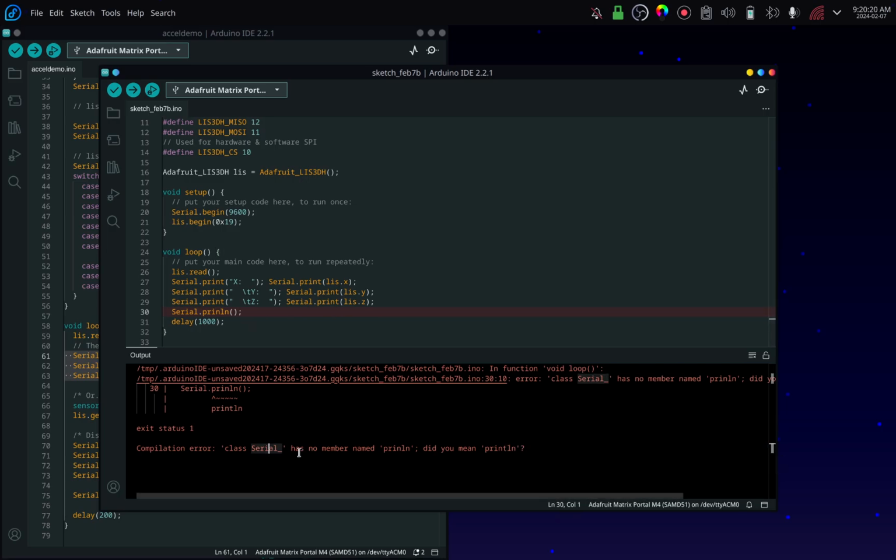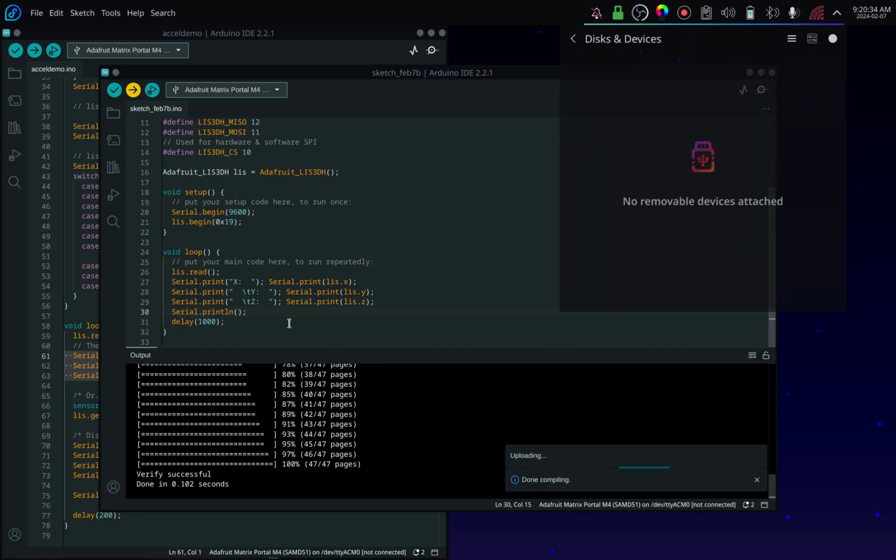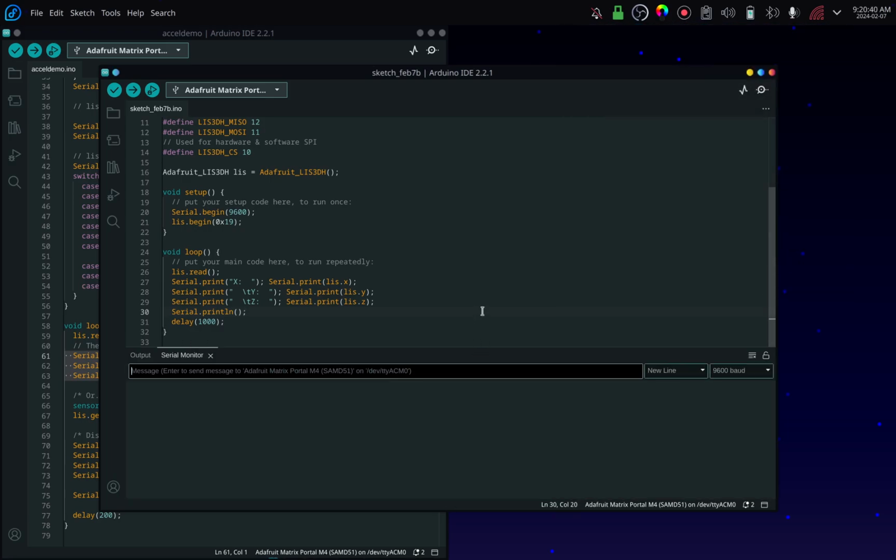So it said class Serial_ has no member named... Oh, I just forgot a T. println, not print line. So Control-U, upload it again, and we're going to see if it works. The way we're going to see if it works is by opening up our serial monitor, Control-Shift-M, once I get focus back on this, and seeing if we are getting data. So we are getting the raw data from our sensor, X, Y, Z.